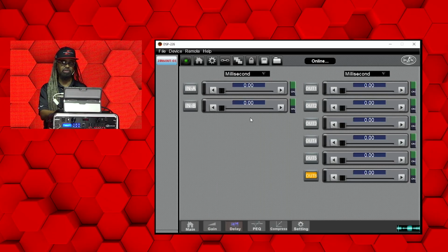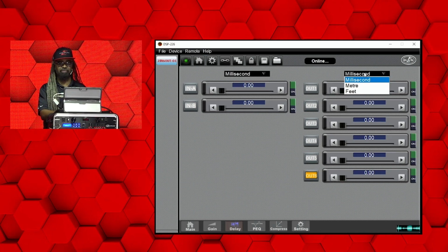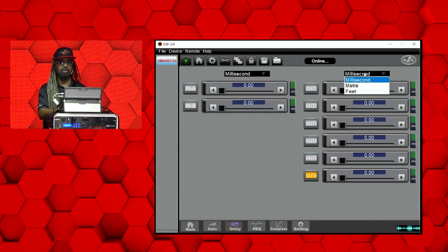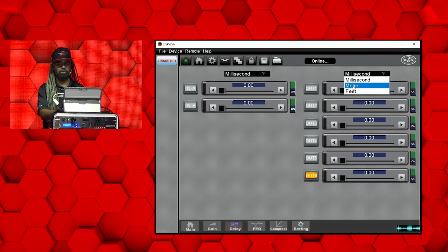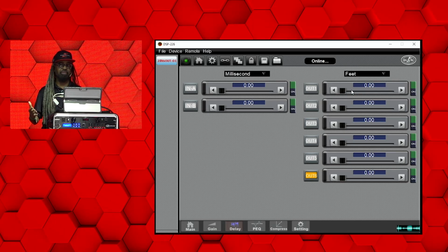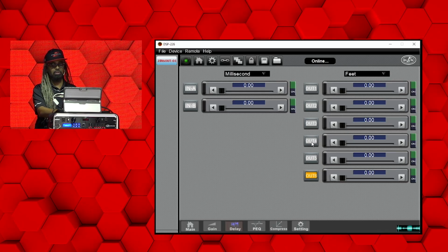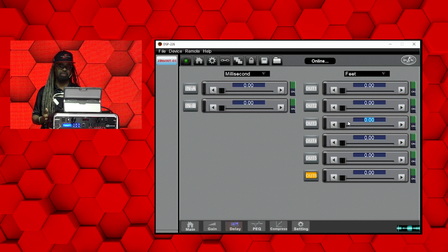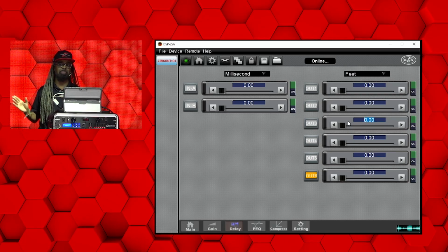Next, we have the delay settings. Depending on if you've measured it yourself in advance, or if you smarted the system and you're trying to tune something, or if you're doing something very simple and basic, your settings for milliseconds, meters, or feet depend on how you're measuring. I typically would go off of feet, and I would delay, for example, my subs, which are on outputs 2 and 3. I would delay that, the measurement or the number of feet that they are in reference to where the main hang or the main PA is.